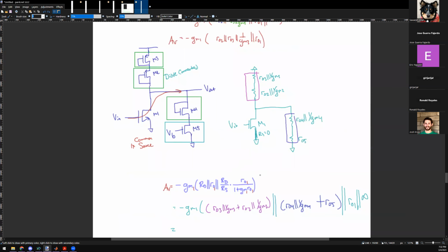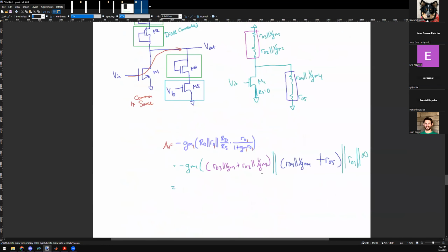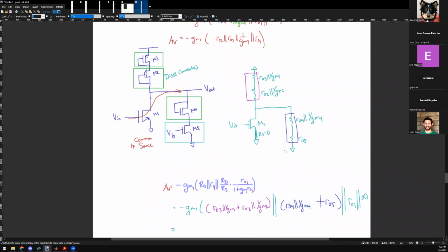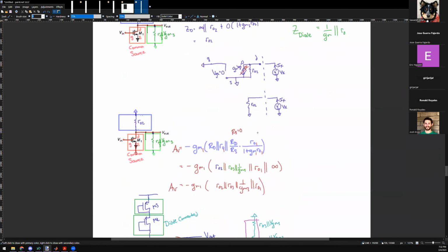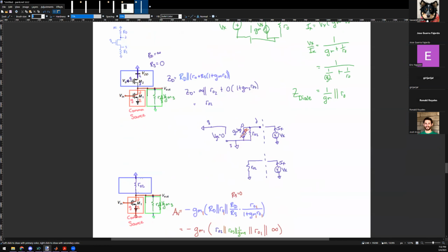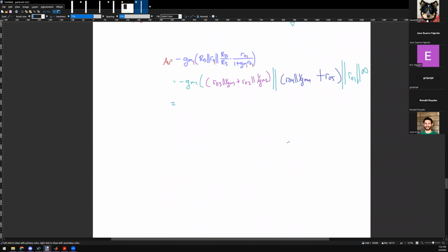I have one question regarding the small signal analysis. You've done one for NMOS, but what would the PMOS look like? For PMOS you draw the exact same thing. What do I mean by that? What does a small signal model for NMOS look like? There's a gate, a drain, and a source. Is there any connection from gate to source?